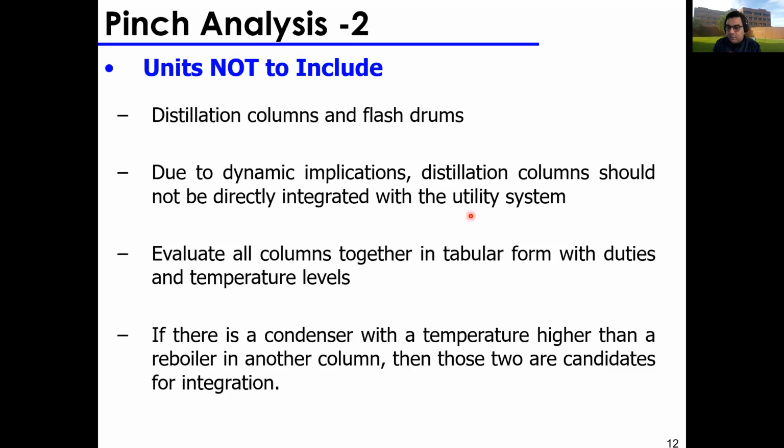If you look at your mass transfer, for example, if you increase your temperature by 4 or 5 degrees, you get a huge difference in separation. If you change your composition by a few degrees without changing the feed stage location, you get a huge difference in your product streams. So distillation columns are very sensitive to temperature, unlike other equipment.